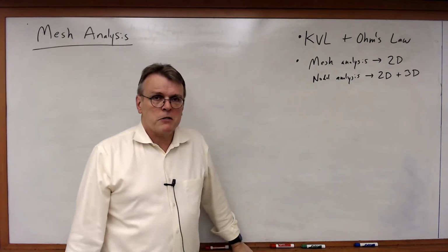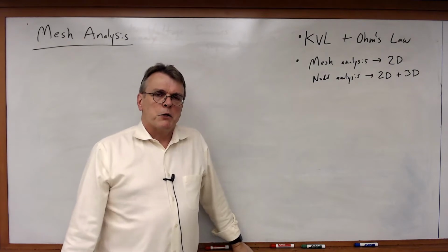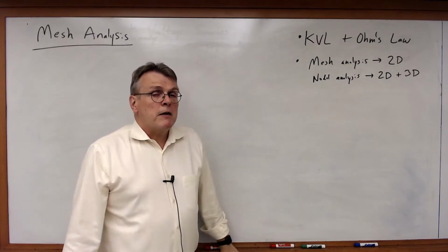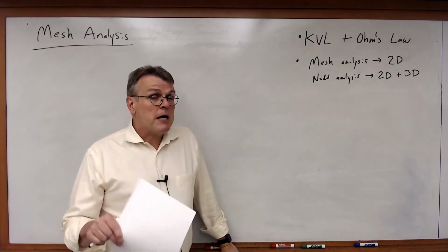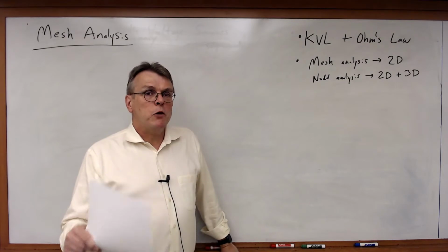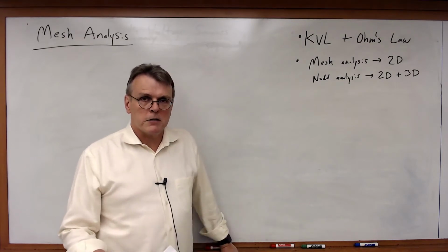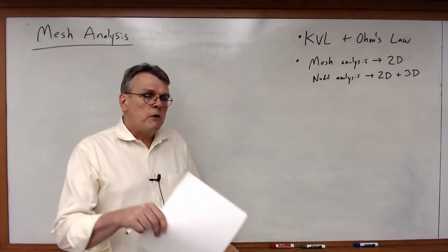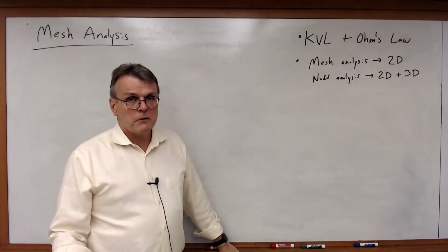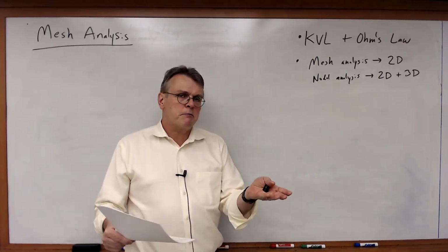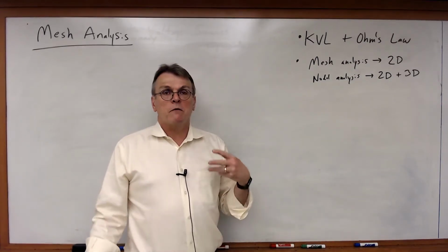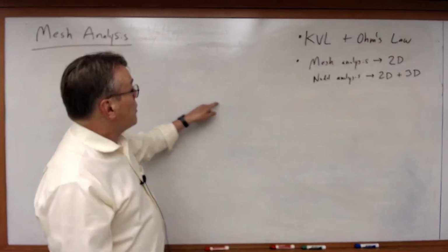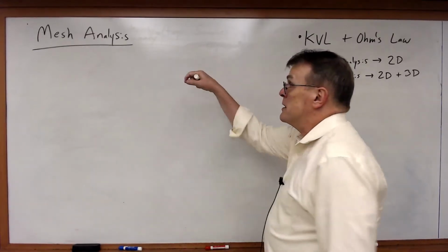Having said that, given the fact that nodal analysis can solve any problem that you can solve with mesh analysis, why do we bother to learn it? Well, as we're going to see later on, the reason why we learn mesh analysis is because with mesh analysis, some types of problems are easier. They give us fewer equations than if we use nodal analysis. And of course, the reverse is also true. Some problems are easier to work with nodal analysis than they are with mesh analysis. So between them, these two techniques essentially complement each other in terms of finding the optimal solution with the fewest number of equations.